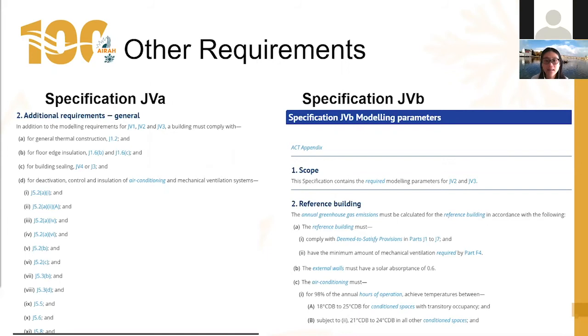There are some additional items if you are a modeler by trade. Just be clear that with the controls strategies, you need to ensure that both the reference building and the proposed building have variable temperature controls for both your chilled water and hot water systems. So you can't have your reference building running a chilled water plant and hot water plant with very inefficient constant temperature designs.